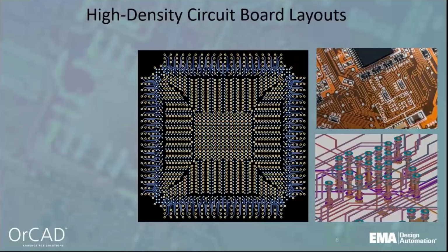When working with high pin count devices such as FPGAs, you're going to see a lot more high pin count devices in there. Traces are going to be made much smaller. They are routed closer together. Micro-vias are used to route signals throughout the inner layers.